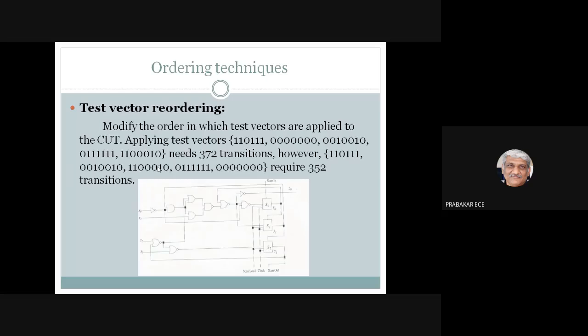We started with IoT, and in the case of IoT, we can go for two types of devices. Either we can go for something embedded where we can deploy a microcontroller, or we can go for an FPGA. In the case of a microcontroller, the low power design possibility is almost minimal, I mean, the possibility of reducing the power. The only option is to go for a reduced frequency. But if you go for an FPGA, then there are plenty of opportunities for reducing the power in terms of design and all those things. So I have discussed so many methods by which you can reduce the power consumption in FPGAs for different applications like IoT. This is my summary.